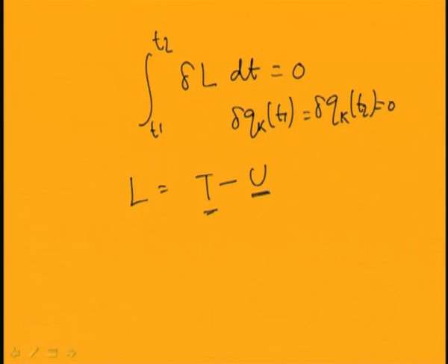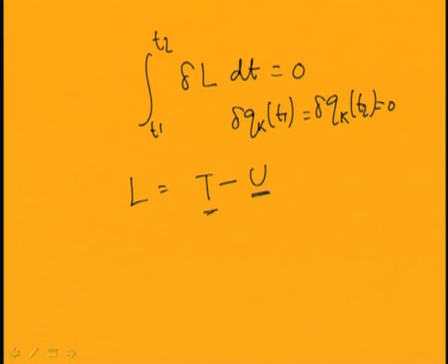That is why one can use the Lagrange principle or Hamilton principle for multi degree of freedom systems and continuous systems. As you can see, for a continuous system the kinetic energy and potential energy equations involve integral and differential terms. So the application of the Lagrange equation will be slightly difficult. One should go for the Hamilton principle to derive the equation of motion.